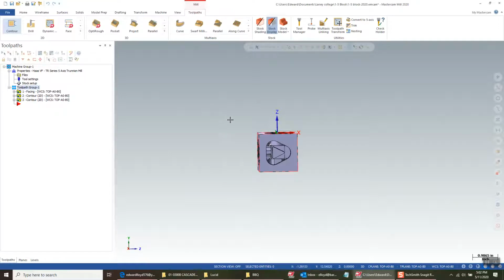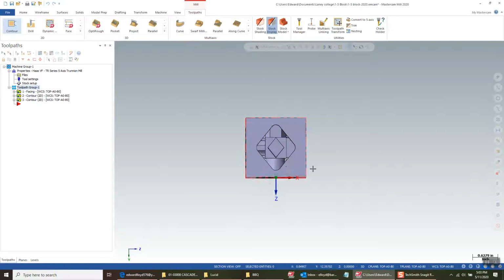So you don't really want that because you want to be able to see the part. So you're going to rotate it this way so that the body will be out here towards the back wall of the machine, and your visibility is unobstructed by the unit. So this will be our second face.